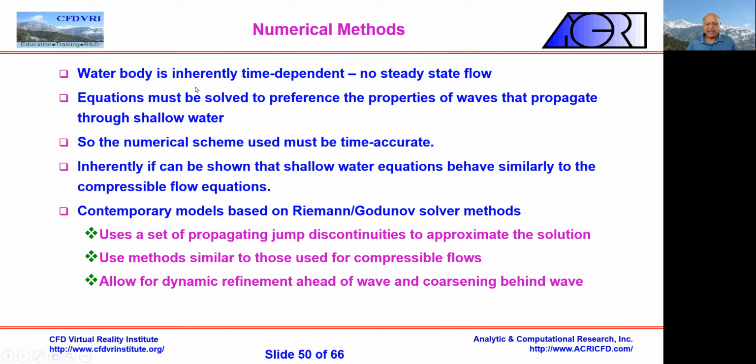A water body is inherently time dependent, no steady state flow. So it's pointless trying to solve a steady state. There is no such thing, okay? And we are going to do a numerical scheme that must be time accurate, okay? Otherwise, you would lose track of the waves that are very important in distributing these heights.